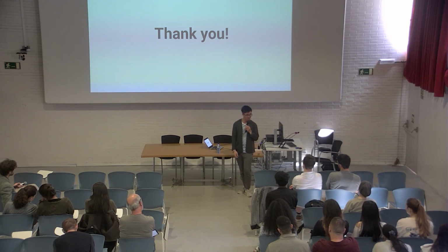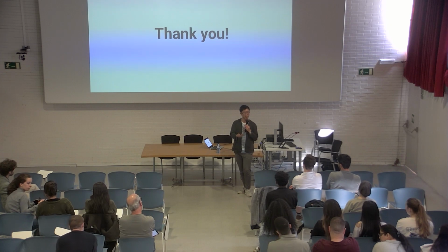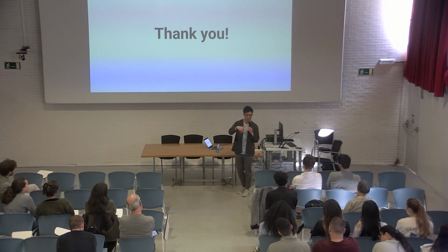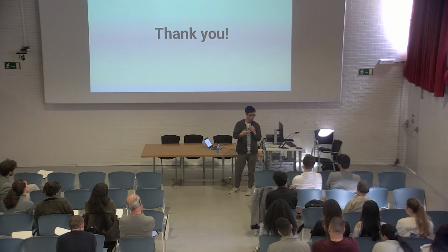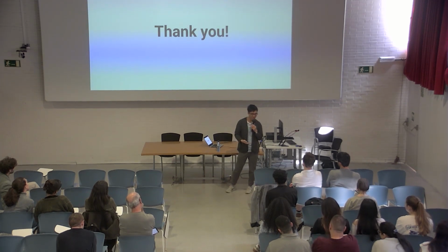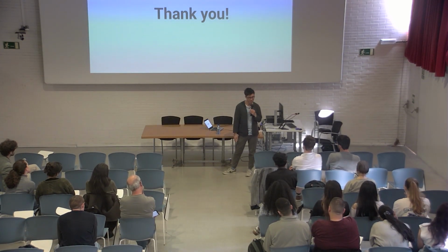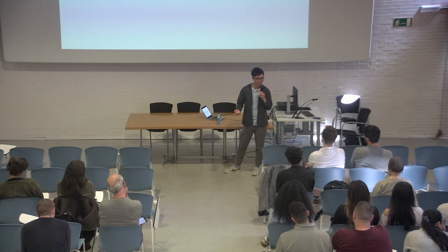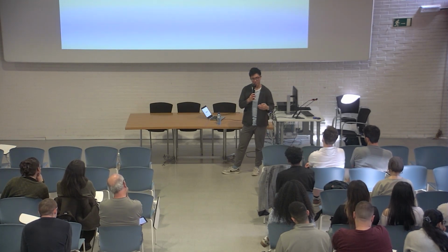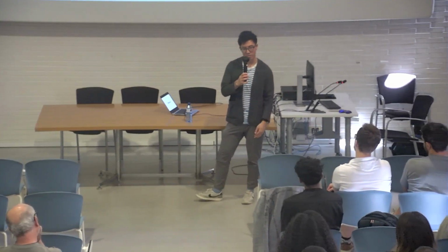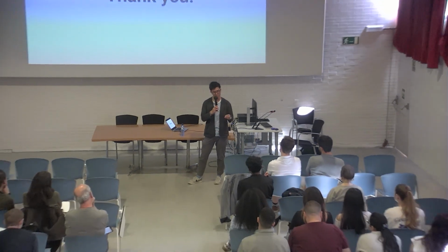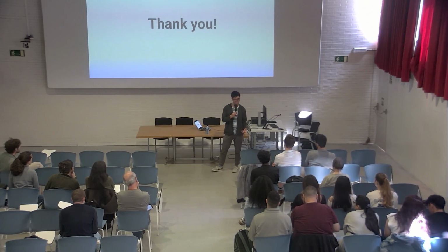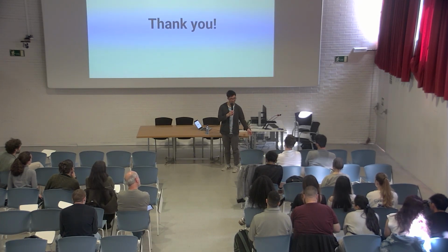So that they can be structurally sound. One of these parameters was making sure that every rope was at least connected, so that they're not flying, of course, that they were interconnected with each other, but also connected back to the main structure. So there were two key drivers of how the optimization process worked. If you start to say that everything's up for optimization, it gets very, very complex. And what we've found is that a lot of the projects we work on nowadays are not really optimizing global geometries, but focusing on a specific aspect of the project to optimize, rather than letting the computer solve everything for us, right?